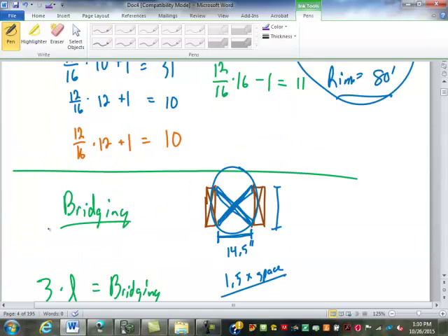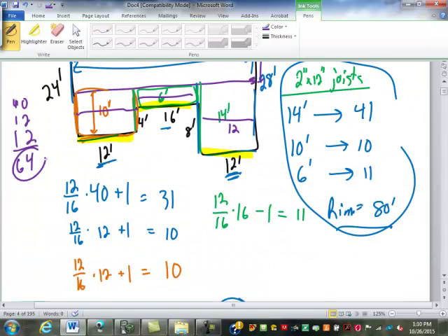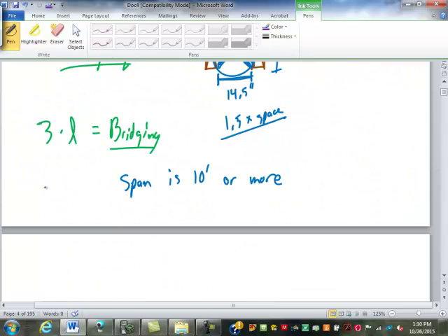So we've got a total of 64 feet that needs to be bridged. So the amount of bridging here would just be 3 times 64, or 192 feet of 1 by 4 or 1 by 3 bridging material. You said if we're over 20 foot, you have to do double. Does that mean you have to do double rows on that 40 foot space? No, I mean over 20 foot of span on the joist. Oh, over span. Yeah, it's the span, not the run.